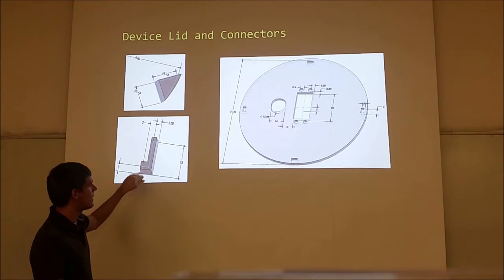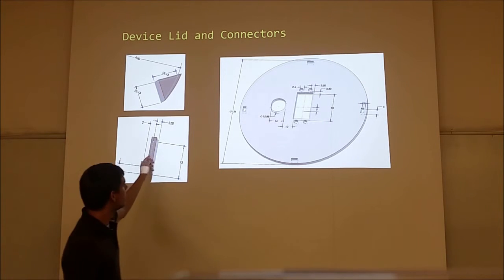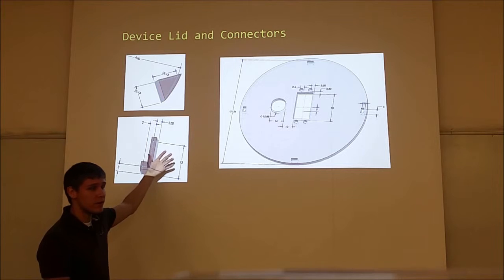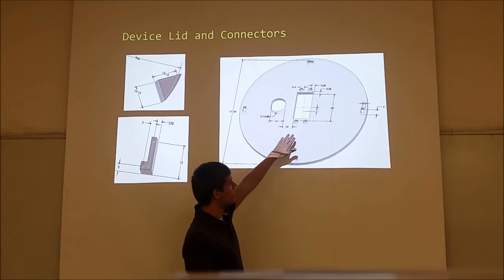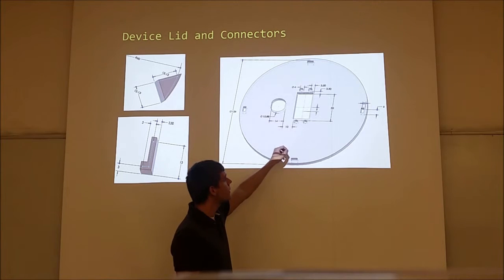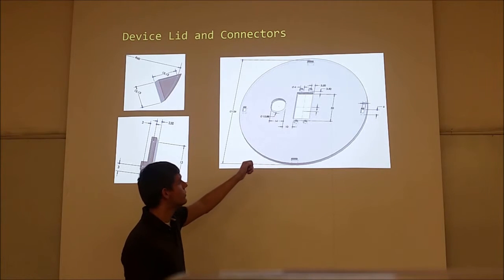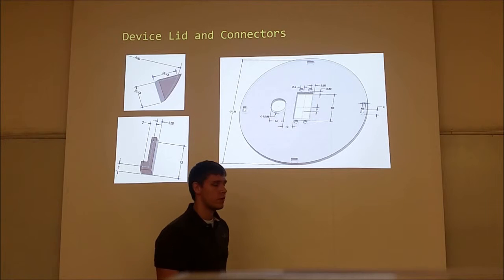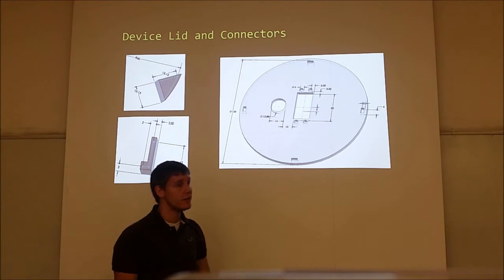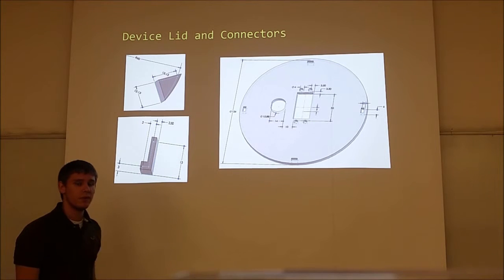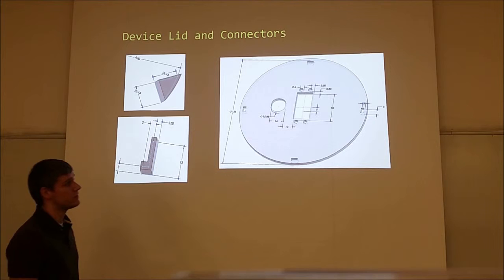These are glued with cyanoacrylate. The holes are drilled big enough for a cotter pin to slide through and lock into place. This is a hole for the hand servo motor, and that's held connected by screws. And this hole is for wires from the tilt servo motor and the LED. And this piece up here connects to the PCB, so it's not wiggling around inside the device enclosure.